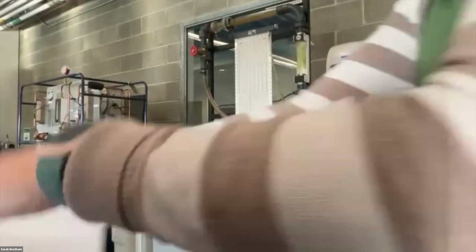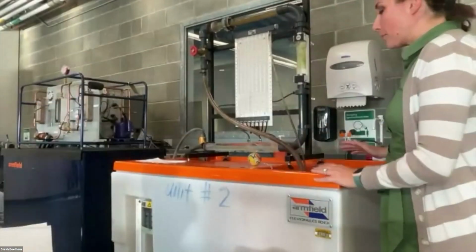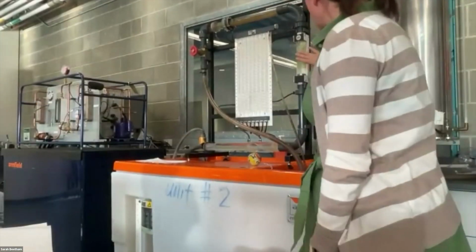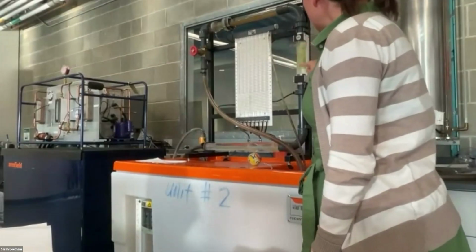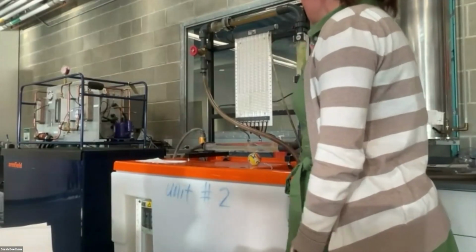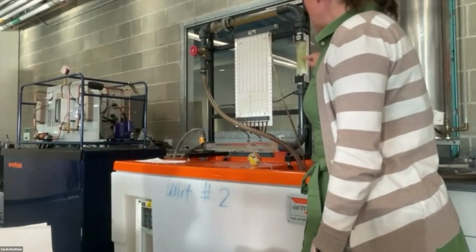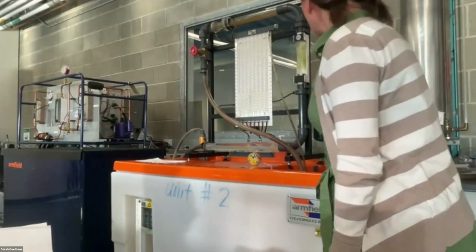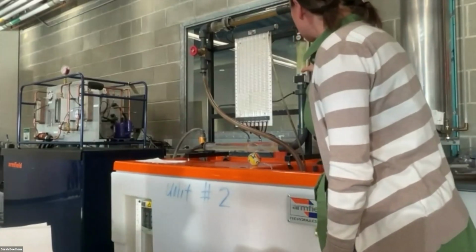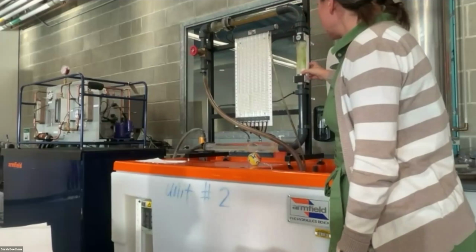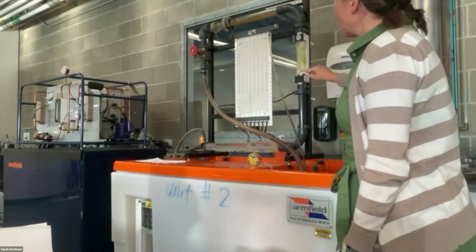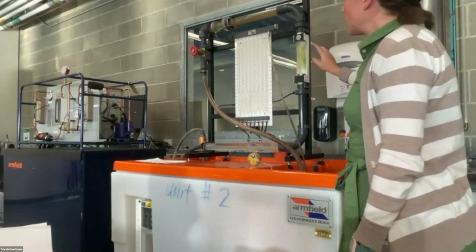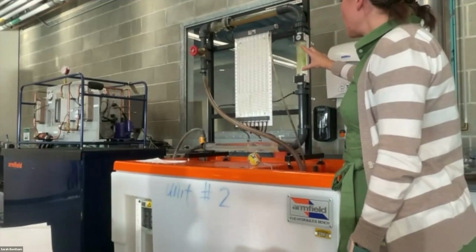Okay, so this is our experimental apparatus. This is our variable area volume flow rate meter. We're not calibrating this one, but we are going to record its measurement. So you'll see that it has marks on it for liters per minute. So make note of the smallest scale on here and make sure that you record it for each test that you do.